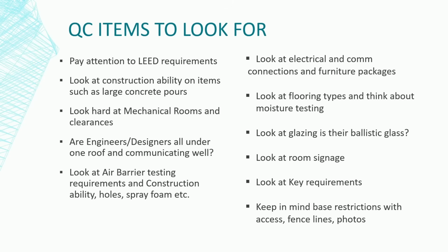Key requirements. You need to look at, is it electric key set? Is it just regular key locks? Is it a federal base? Do they have certain requirements? Are you going to need the manufacturer to send those cores to a key shop and then the key shop gives them to you to install? Are you going to keep construction cores in there and then just turn those over, and then the end user is going to install their own lock set after you go through the procurement of it? If it's an electric keying system, that takes additional training that you're going to need to think about when you're scheduling your training for the end users. So always pay attention to key requirements.